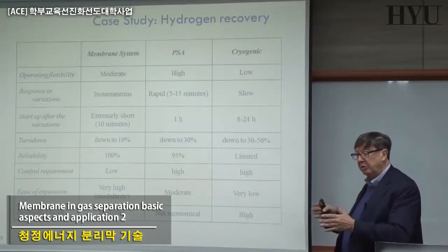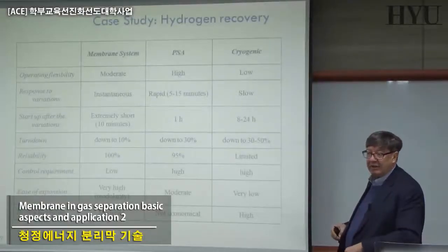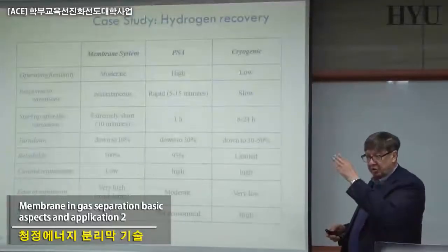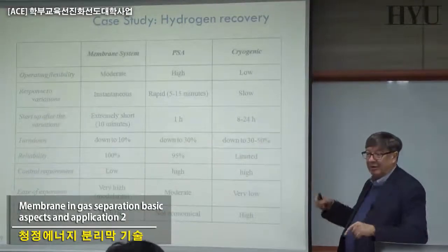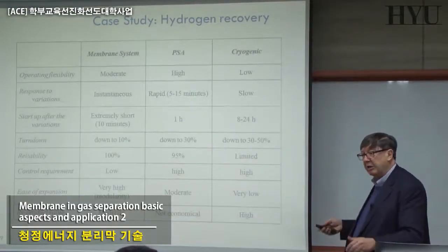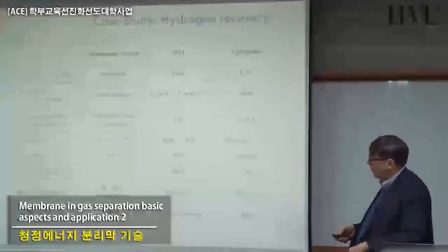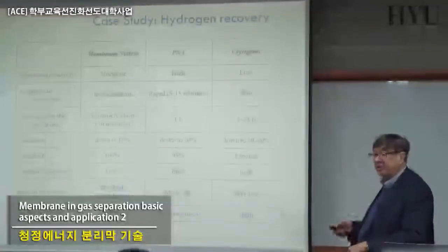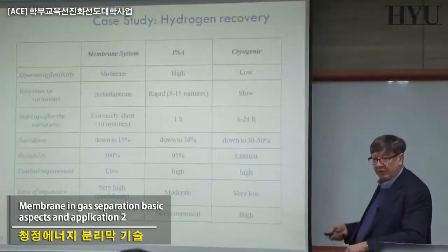You're always assuming that you have a stagnation layer at the interface, where the different species have a linear concentration profile instead of exponential. And with some experience, you can just integrate the system and arrive at some conclusion.